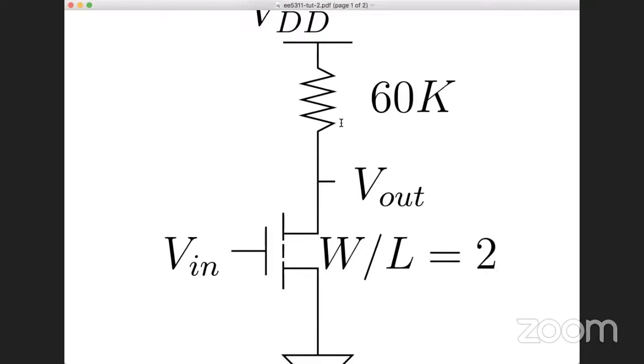The output is taken out at the resistor, right? This is also an inverter only. The VOL, VIL, VIH and all depend on what the structure is internally. What you have inside this IC is something called a totem pole output and some really complex stuff. What I'm trying to say is that what you built using transistors may not be the same as what is inside the IC. And if you change the transistor structure, the VIL, VIH characteristics will change.